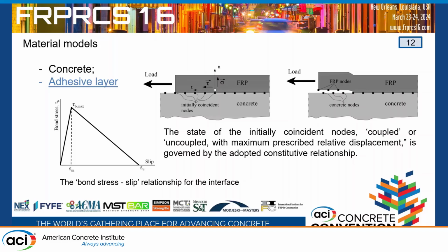So I can prescribe the relative displacement of nodes as a function of the opening. It's a user-defined element? Just a custom procedure to govern nodes. Okay. Because you're using the inclined direction to pull out, it combines fracture mode 1 and mode 2, pulling with shearing. Yes, but we are not using fracture mechanics.